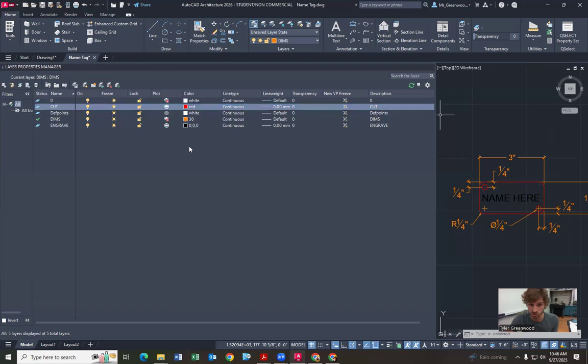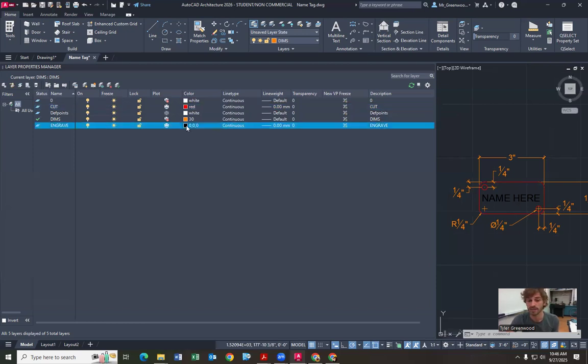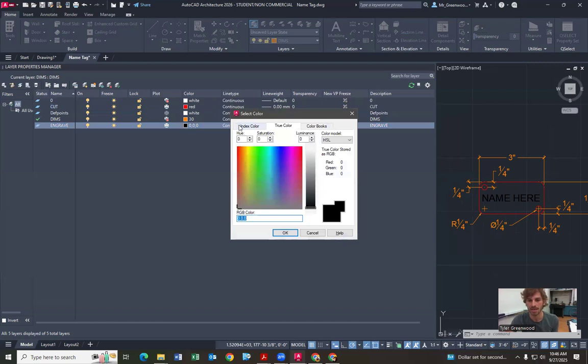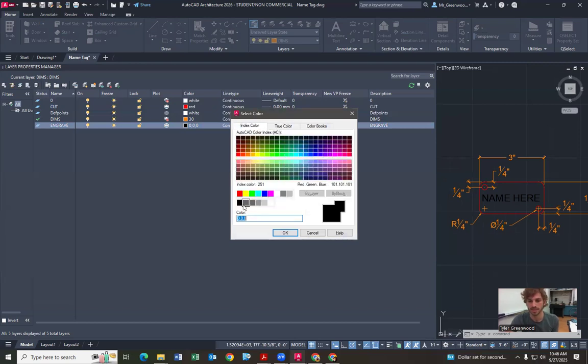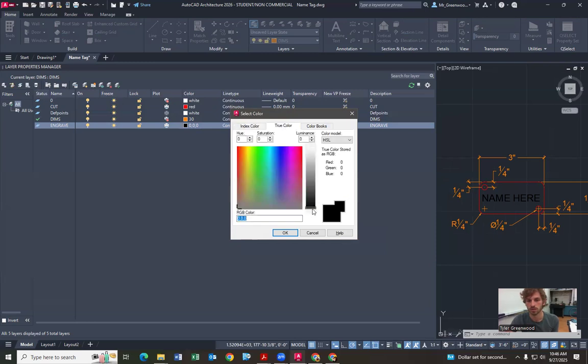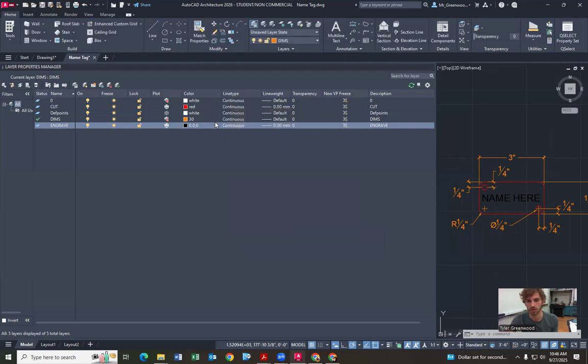this is essential. You need the right color. If you are engraving, you need pure black. 0, 0, 0. If I select 250, it won't work. I need 0, 0, 0. So make sure you are selecting 0, 0, 0 to engrave.